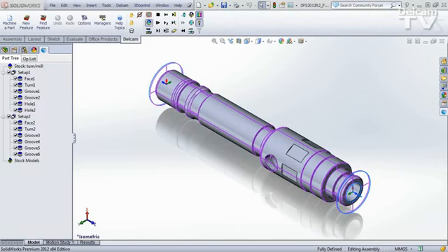Combined part transfer is now fully integrated into DFS 2013 R2. Transfers can be selected from slug transfer, reverse slug transfer, bar pull, and part support. Cutoff operations also contain part handling capabilities. Posting and simulation functions will be supported by this new feature type.